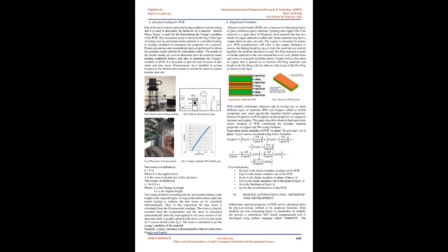Problem definition. The PCBs are widely used in all the electronic devices or equipment, and their mechanical properties will differ from PCB to PCB based on the number of layers and thickness. Since there is no proper data available on PCB orthotropic material properties, most of the FE simulations have been carried out using isotropic material properties, which affects the accuracy of virtual test simulation results. Hence, in the absence of material test data, it is necessary to evaluate the orthotropic material properties of PCB using empirical formulae to obtain accuracy in the simulation.